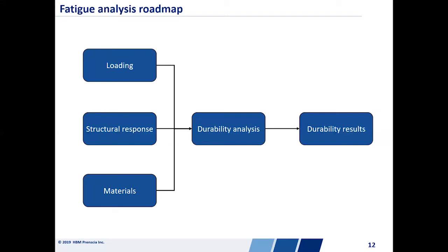Lastly, the structural response for DesignLife, this is essentially your FE results. And again, if you've done something like this before, you've probably done a linear analysis, a linear static analysis in FE and brought those results into DesignLife. And what we will be doing here is actually a frequency response analysis in FE. Therefore, we're going to have real and imaginary stress results across a range of frequencies. And that is going to be paired up ultimately with our loading that's also described in the frequency domain.